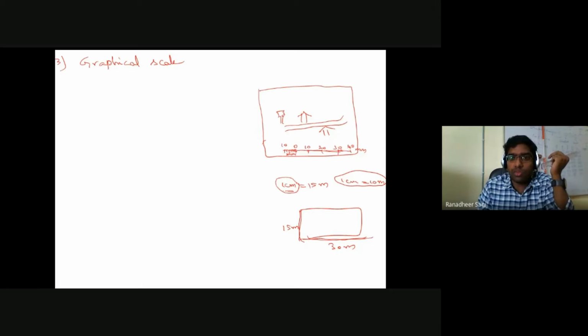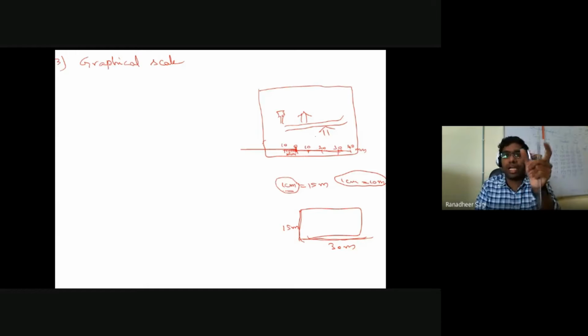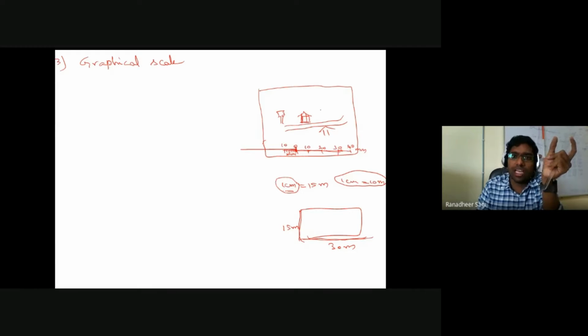Now, 2 centimeters means, if I place my scale here and start measuring the required dimension, 2 centimeters means this 10 divisions, another 10 divisions, so 20 divisions of that dimension I have to mark, and accordingly I have to represent with that respective dimension. In this length direction, a 2 centimeter line is to be indicated. In the width direction, a 1 centimeter dimension is to be represented. Likewise, I will be representing everything I have got according to the dimensions being transferred.